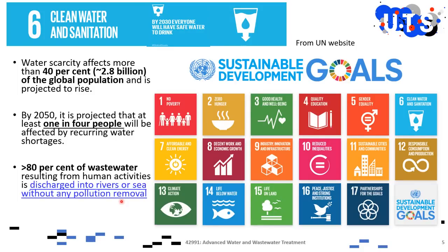From manufacturing industries, the wastewater is just directly dumped into the rivers and seas. This definitely will affect the water quality of the receiving water. If you're dumping into the river, it will receive a lot of biological matter, and increasing the BOD of a system will result in a very polluted case, and this will degrade much of the water quality. So the receiving water will not be available anymore for further useful use. This is the main problem at this point.